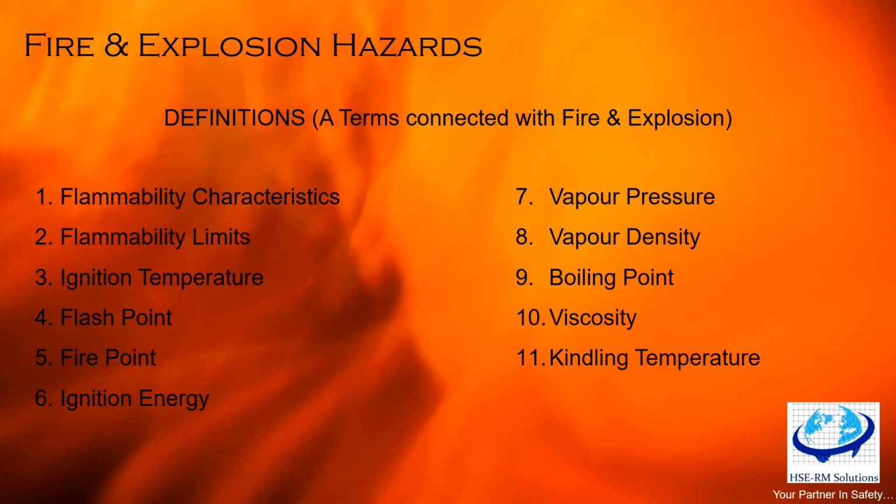So what are flash points? We explained auto ignition temperature. Auto ignition temperature is a temperature which is abnormally rising, because of which the ignition happens. But when we talk of flash points, there are two methods: open cup and closed cup.